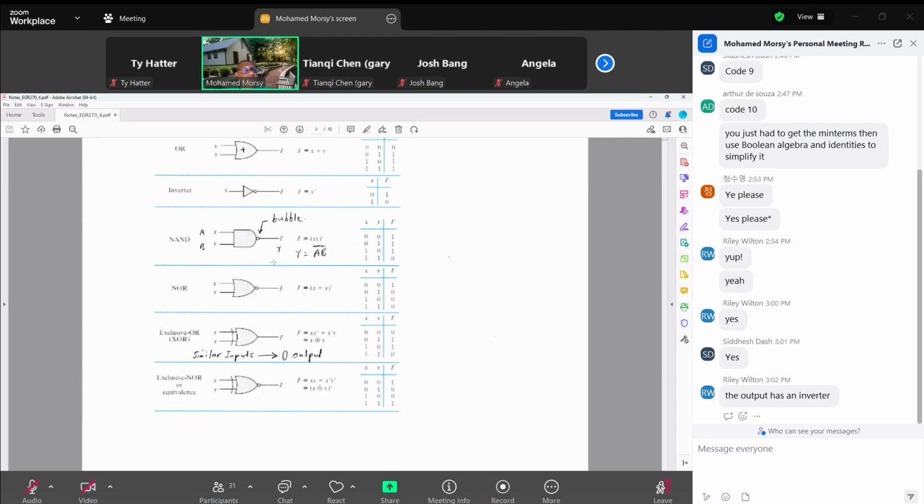So for the truth table here, X and Y 0, 0 for AND, you can open another column here. So 0, 0, put 0. 0, 1, put 0. 1, 0, put 0. 1, 1, put 1. And then the last column, which is the output F, invert what you got. So 0 inverted to 1, 0 inverted to 1, 0 inverted to 1, 1 inverted to 0.